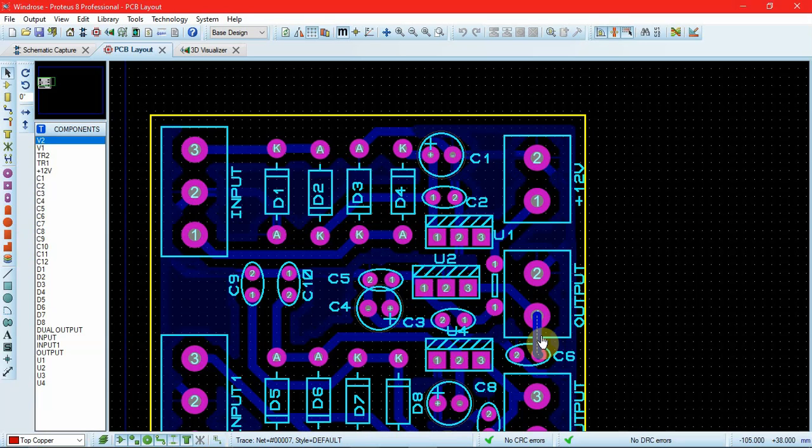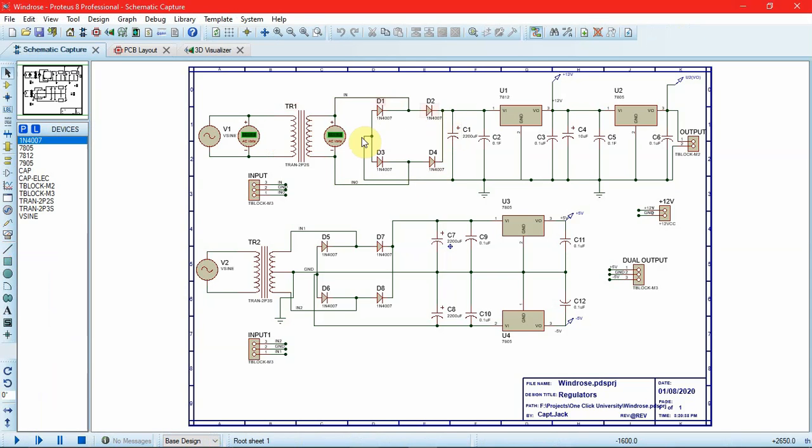The capacitor should be placed close to the signal entering a particular device or board. Let's see the demo. In the schematic, we can see that just after the rectifier bridge, the capacitor is used as a filter and then as a noise reduction component.